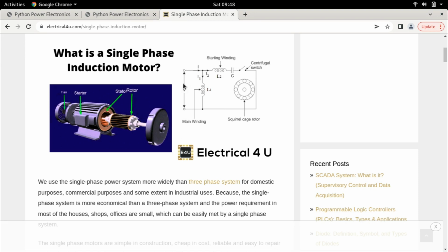So here this voltage V is the input applied voltage, right? So typically if you have something like, for example, a stator, you might have some terminal somewhere here, could be anywhere. And you usually connect your input voltage there, right? So that means you're connecting a single phase input voltage at some terminal in this stator. That could be either 120 volts 60 Hertz or 240 volts 50 Hertz, wherever you live in the world.